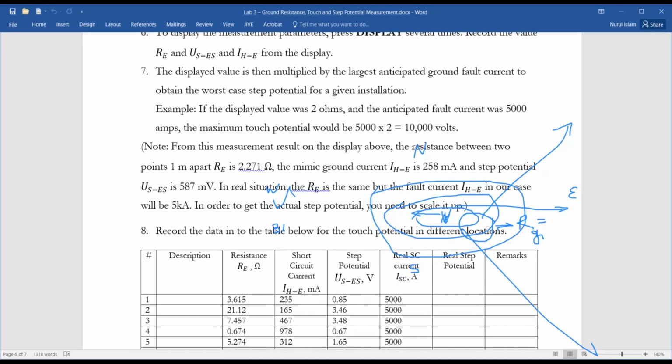Okay, here in lab you are measuring ground grid resistance and modeling your grounding grid. You will calculate ground grid resistance. So in a real-life situation, you will take the measurements close by an existing electrical substation or station, and all the measurements will be done on your site. Whatever information you have from your system, you will put in WinIGS and model your grounding grid.